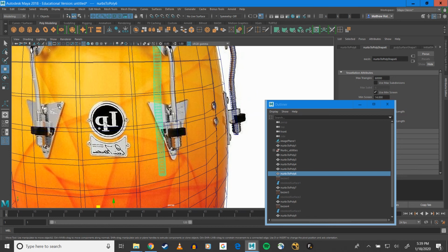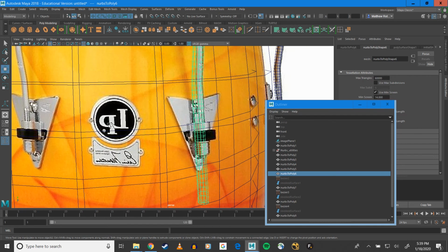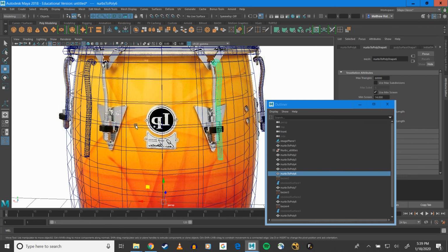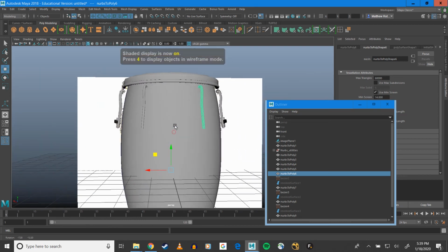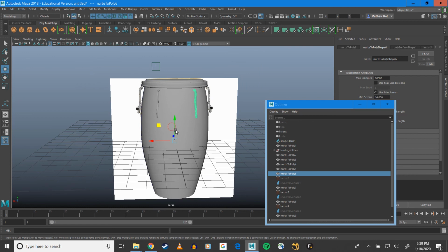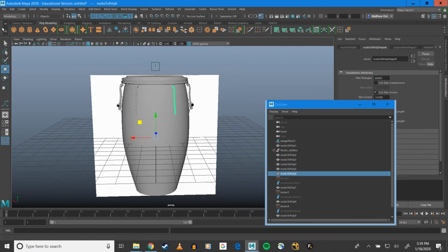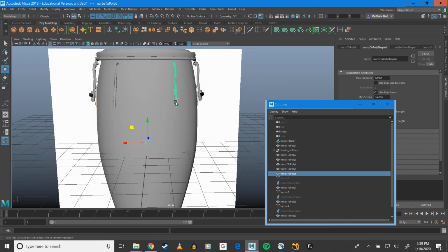I mean, you could make a closed shape and make a lofted surface for these, but that wouldn't necessarily be the best way to go about doing that. What I've made so far is really what would benefit from being made using Nurbs curves, and the rest I would just make with poly geometry, starting with my various polygon primitives.